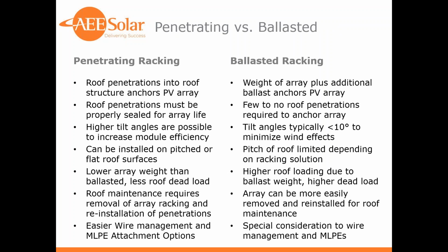So just quickly comparing penetrating racking versus ballasted racking. Penetrating racking, of course, you have roof penetrations into the structure that anchors the array. Ballasted racking uses a combination of ballasting and maybe selective penetrations. With a penetrating array, we have to make sure that we seal them properly. With ballasting, we don't have to worry about that since we're typically not penetrating the roof unless it's seismic or